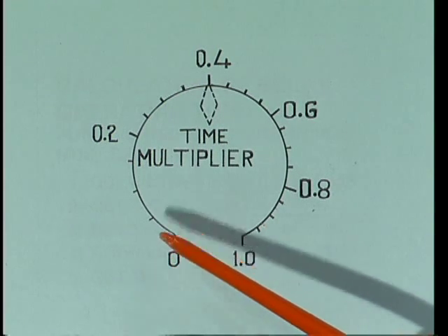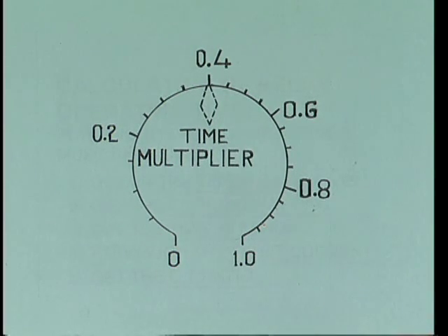The relay should operate in 3 seconds, provided that the current crosses its pickup value. That means two values are set: the current setting and also the time setting. When the current exceeds its pickup value, then at 3 seconds the relay should operate. Like this the relay operates.